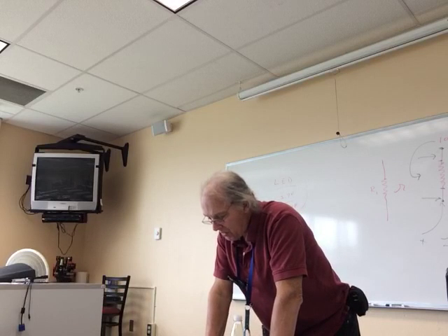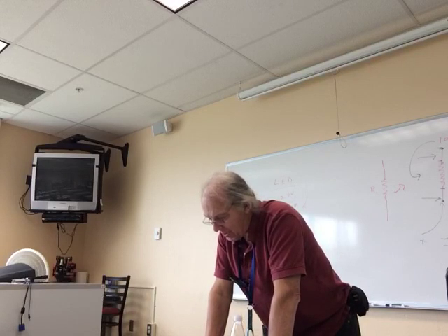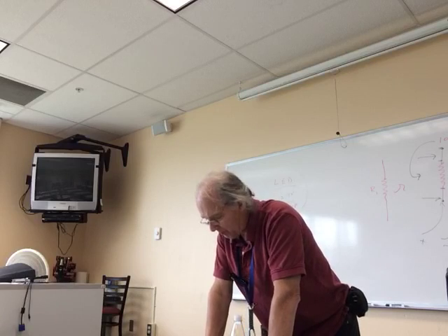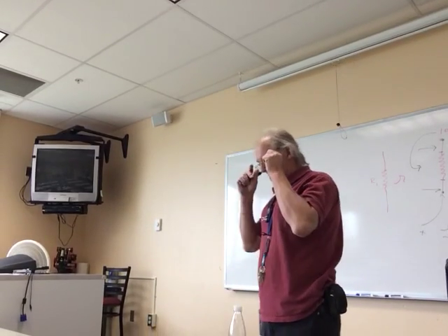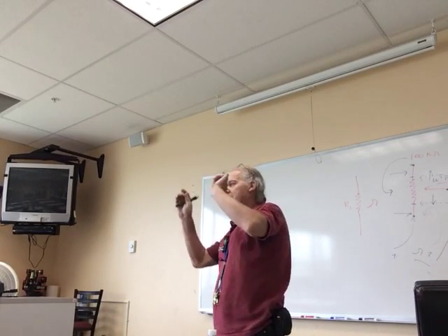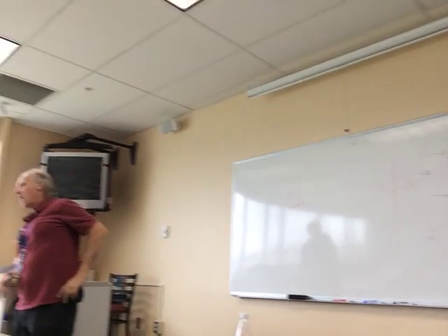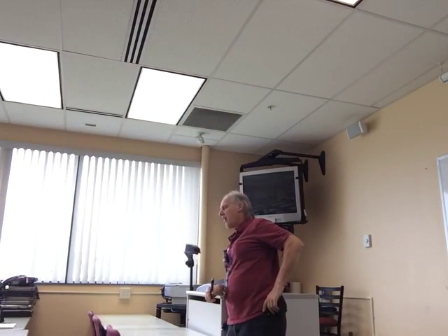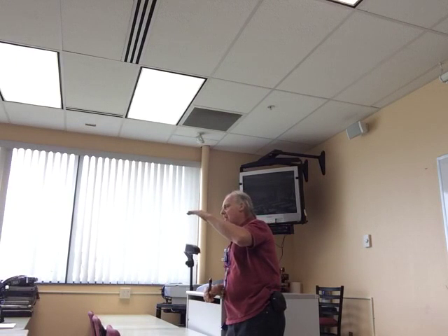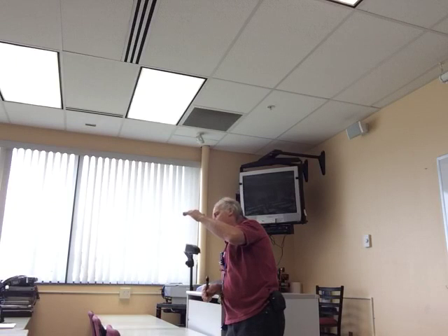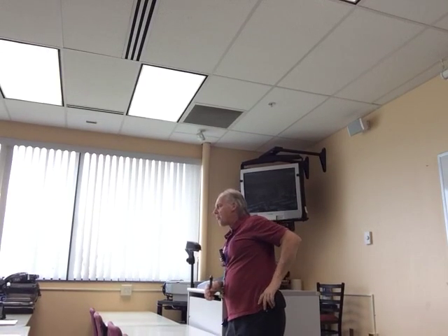Now, if you look at figure 8-14, they have a pot, don't they? Notice the pot's in the center. It's not all the way up, not all the way down. It actually produces a voltage divider by using a pot. Kind of fools you. It's not two resistors, but when it's in the middle, say 100K, that's 50K on each side. So that makes a 2 resistor voltage divider. So that would be a variable output voltage divider. Again, so that we can bias something or something that doesn't draw a lot of current. We can use it on it, okay?